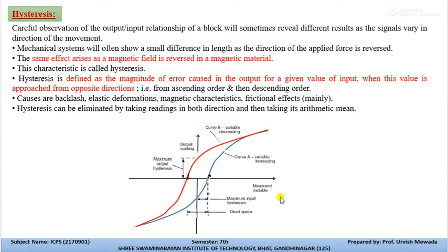That reversed field can oppose the motion of the pointer, or the result shown by the instrument. This is because of the hysteresis, meaning all magnetic material has the tendency to store magnetism, even if it is not supplied with electrical input.